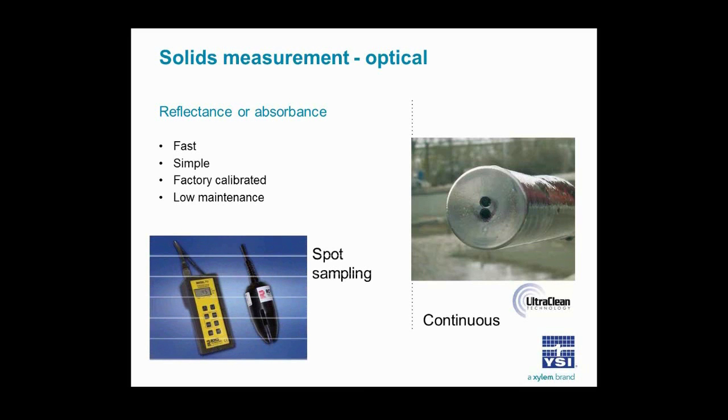Spot sampling is also very commonly done, and it can be done with a handheld like this one shown here. But one caution I want to offer is that the TSS, the spot sampling sensor, is generally not factory calibrated, and so needs to be calibrated in the lab before taking it out to the basin. So especially when you're verifying measurements, you want to have a properly calibrated handheld sensor.